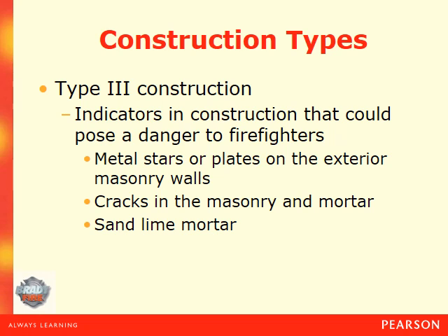Cracks in the masonry or mortar, or sand lime mortar. And sand lime mortar is one of the first types of concrete that was produced, and the reason you're worried about it is it's water soluble, meaning that it can dissolve over time, of course, with rain or with water from a fire hose.